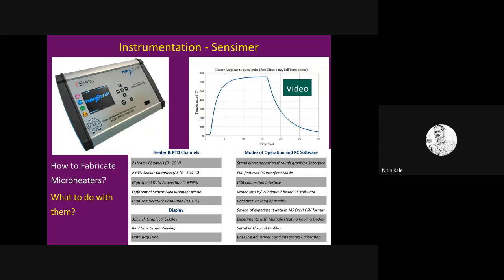Now you can have a calibration situation. You put 1, 2, 3, 4, 5 grains of salt, and you find how much is the change in rise time. That could be a very interesting experiment for PG students, or maybe even higher level BTech students at your labs, for sensors, instrumentation, MEMS, etc. These are good kits to play with.